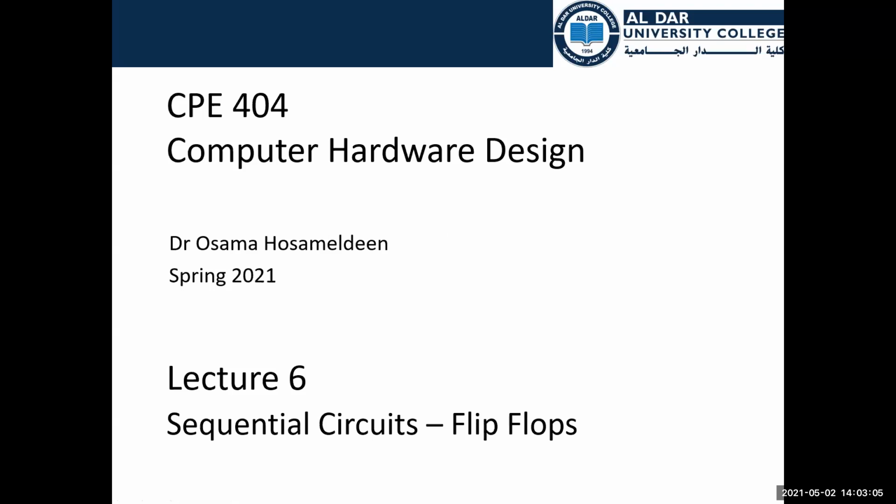From this lecture on, we will speak about different type of hardware, which is sequential circuits that can remember the previous states. It is different from the combinational logic, which is not remembering anything. The output depends entirely on the input. But for the flip-flops and sequential circuits, the output depends on the input and the previous state. We'll talk about this in detail.